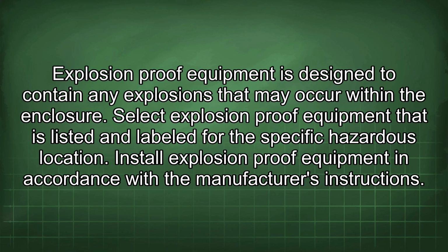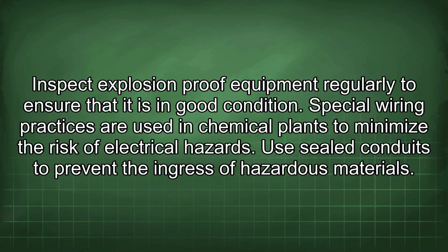Explosion-proof equipment is designed to contain any explosions that may occur within the enclosure. Select explosion-proof equipment that is listed and labeled for the specific hazardous location. Install explosion-proof equipment in accordance with the manufacturer's instructions. Inspect explosion-proof equipment regularly to ensure that it is in good condition.